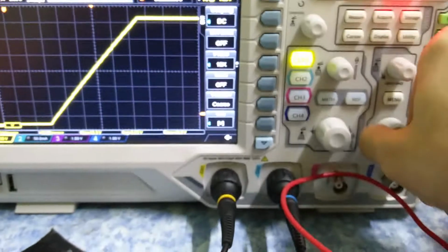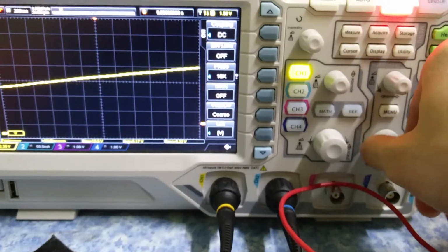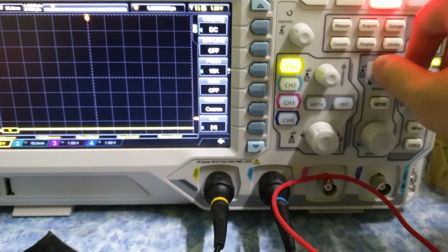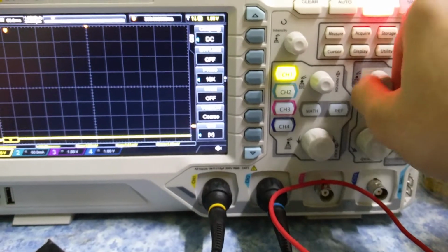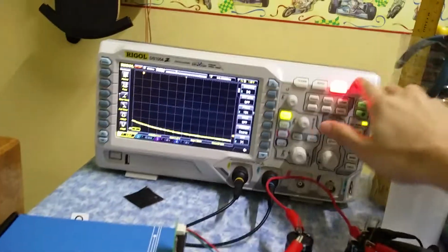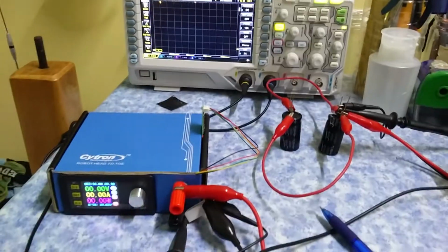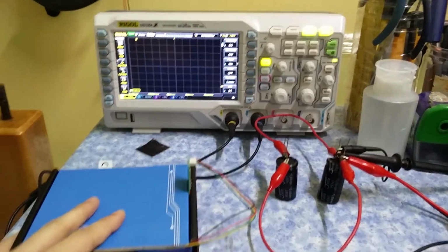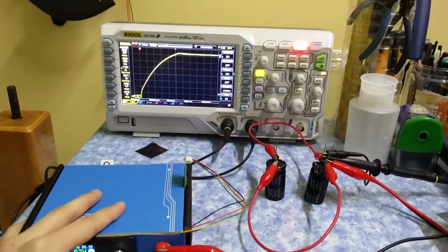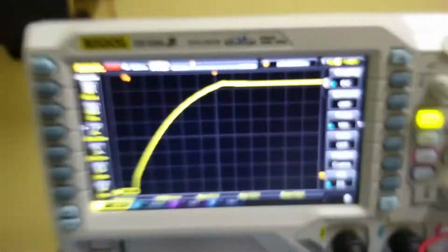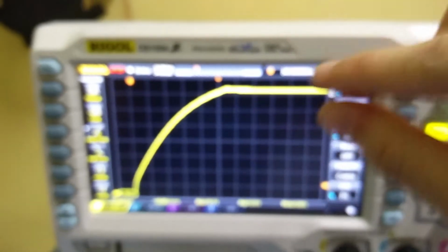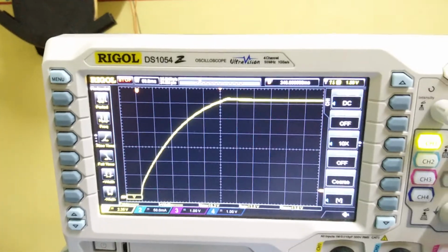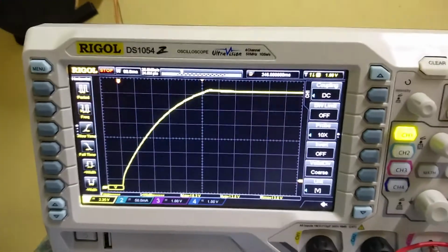Let me set up my scope here. Turn the time base down to say 50 milliseconds. Recentering. Set up for single shot. Oops, forgot to turn off this power supply. Now the apparatus is set up for non-constant current charging. Turning on the power supply. There. Well, my phone's not working with me.